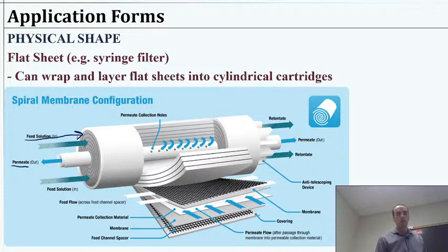And so then we get the feed coming in the one side. Anything that, by the time we've crossed this cylinder, did not make its way into that core area through those channels just leaves as the retentate. Okay, so spiral membranes, spiral wound, pretty interesting.